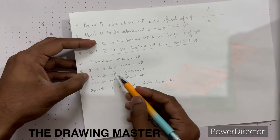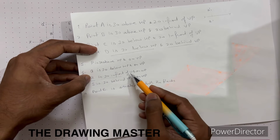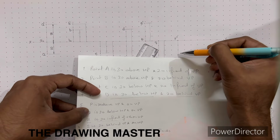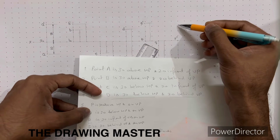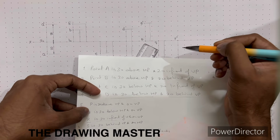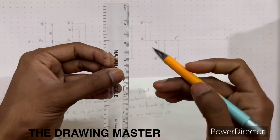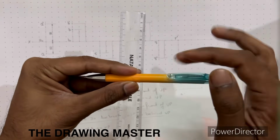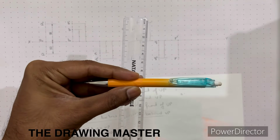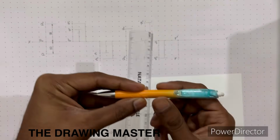You can see point R is 30 in front of VP and on HP. Means it is neither above HP nor below HP. So where will the front view be seen? On the reference line. This is the reference line. The point is neither above HP nor below HP, so front view will be on reference line. Above and below is always front view. Just remember.